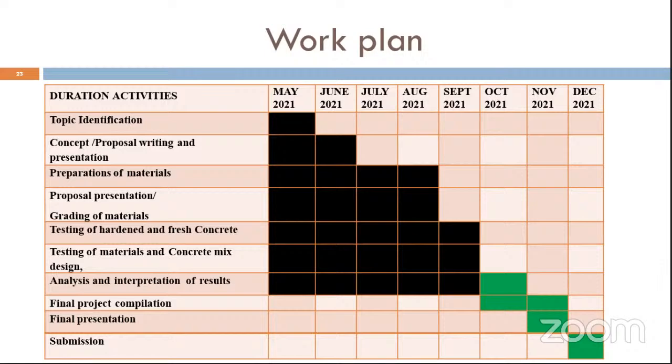And this helps in mix design so that you don't wait for a whole month. From the word go, at 7 days, you could even tell that the mix you designed could not give you the strength, so that you can try another trial mix. So that's why we are saying for this project progress, we need to see the results at 7 days, so that we can project, because you're doing a mix design, and start seeing whether at 28 days you will get the strength or just concrete which has not attained it. Okay.